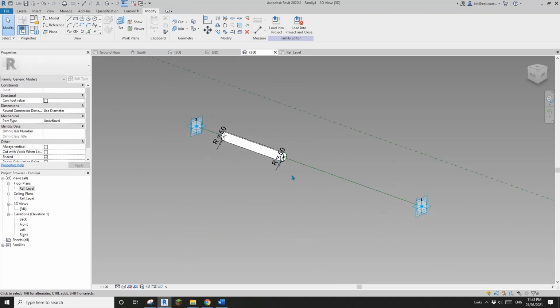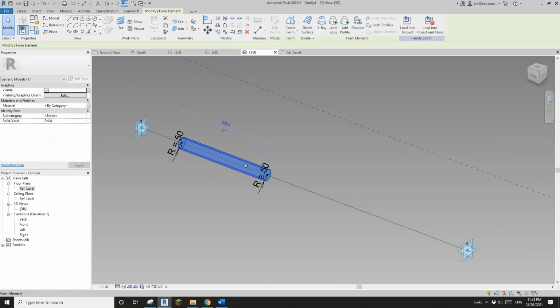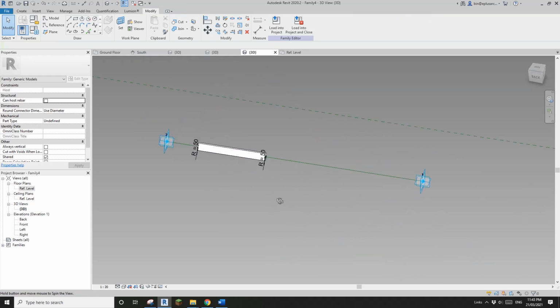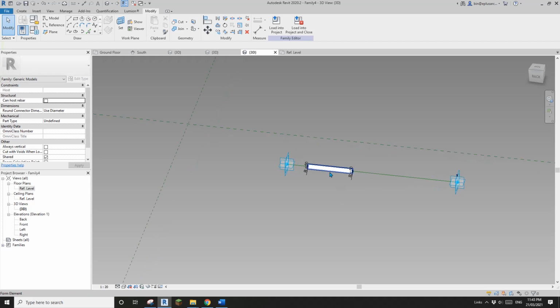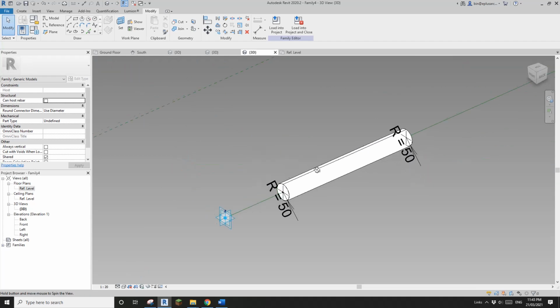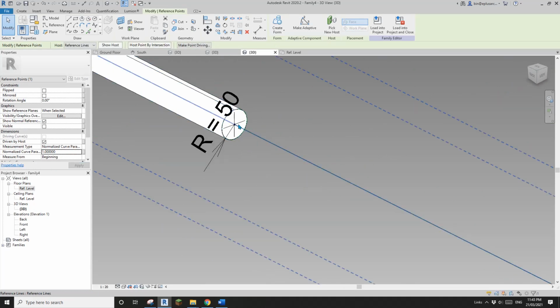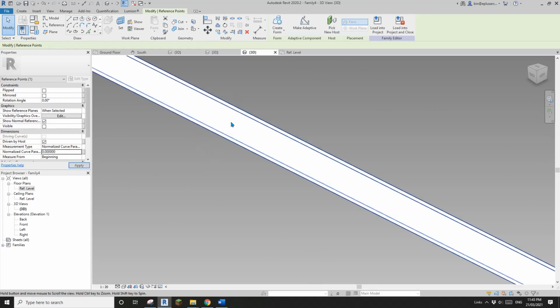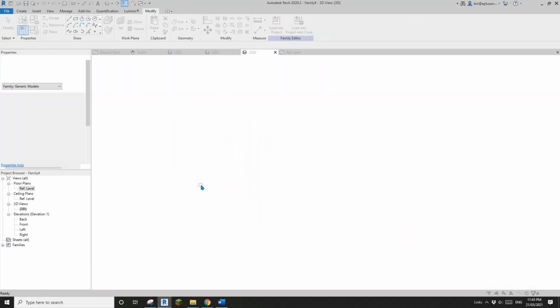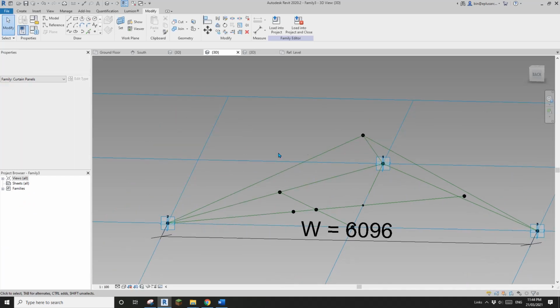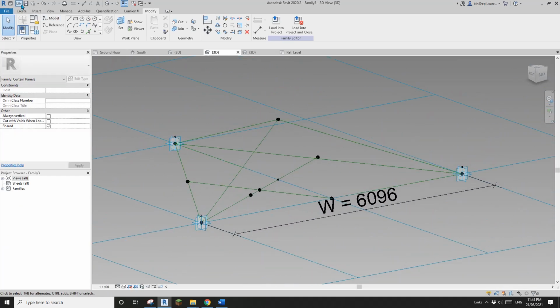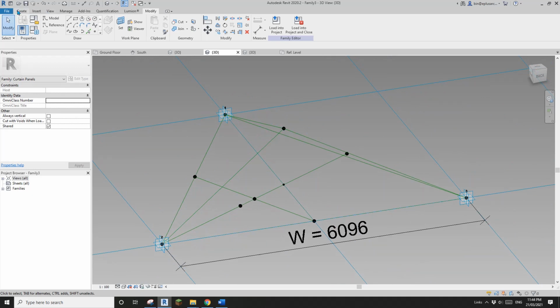Yeah, that's better. So looks like sometimes when you create the adaptive family, it's good to just place them, align them to each other. So don't just randomly do it just like what I did. So okay, so now select this point and move it to 1, and also select this point and move it to 0. Now load this into the family 3, overwrite, and sometimes you will see, oh, it's gone, but don't worry, just if you click on save, cancel, it's gone. It's fine, let's just create again.